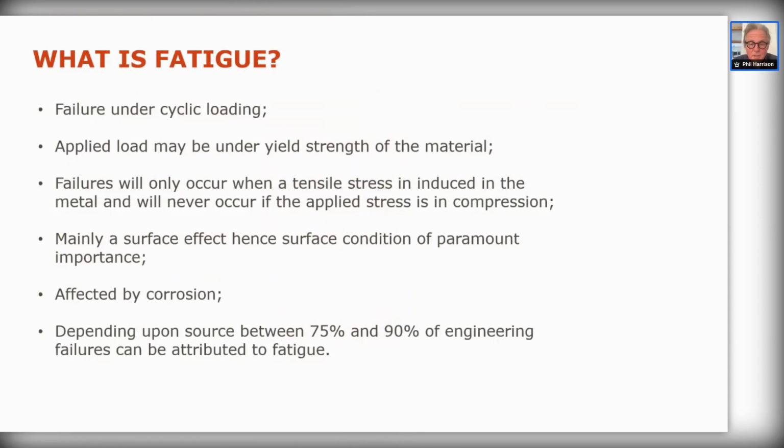It is also affected by corrosion in a number of ways. If a material corrodes, it affects the surface. It creates pits and dimples on the surface of the material. This can be the initiation of a crack. Also, you can get corrosion within the crack in corrosive environments, which can accelerate the movement of a fatigue crack through a material, reducing the fatigue life of the component dramatically.